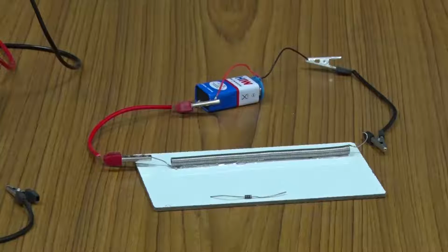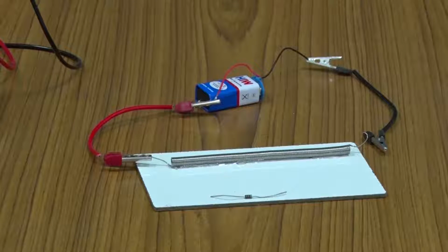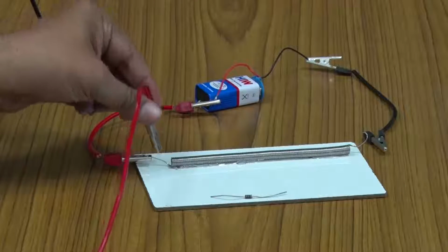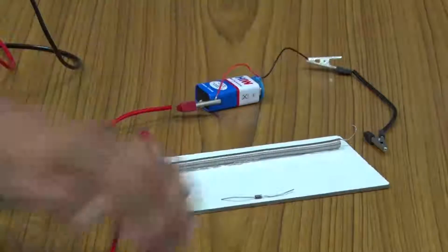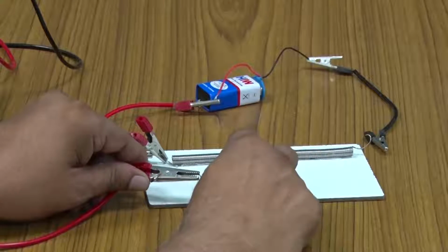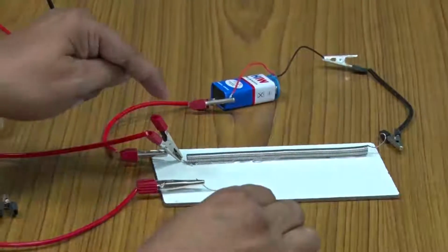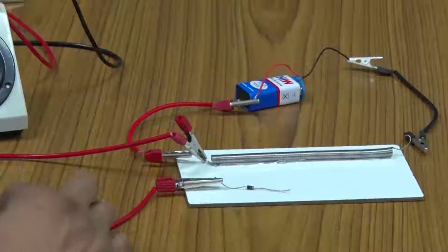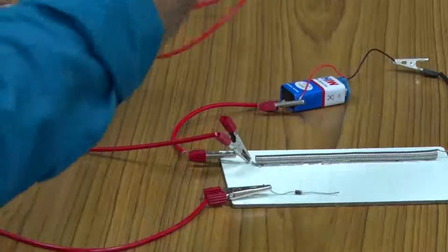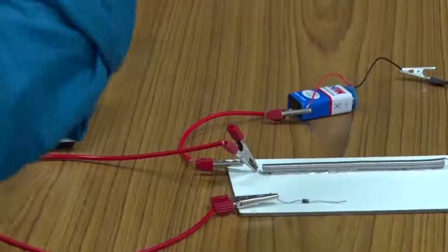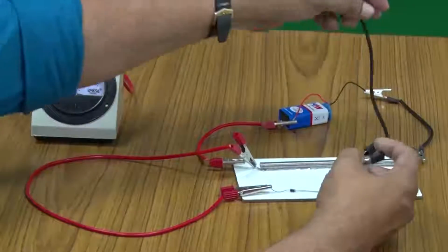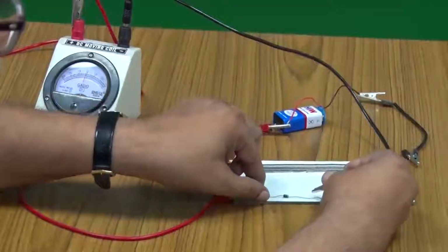And then I take another wire and connect this, the positive end of this potential divider, and I am connecting it here to the diode. So, one side I have already given to the diode, and then the other side I am taking it through this galvanometer, and I am connecting this galvanometer to the other side of the diode.